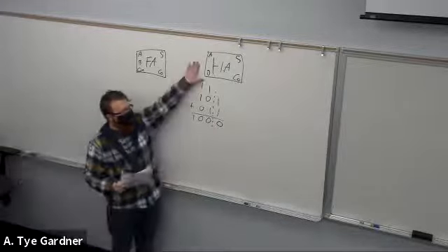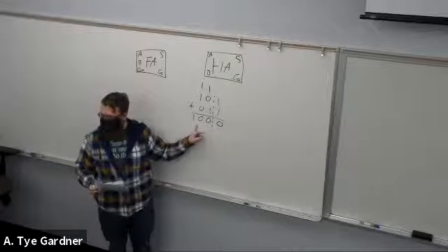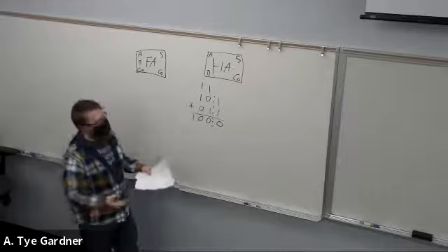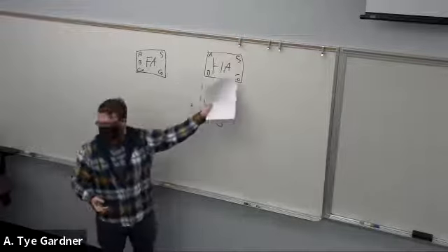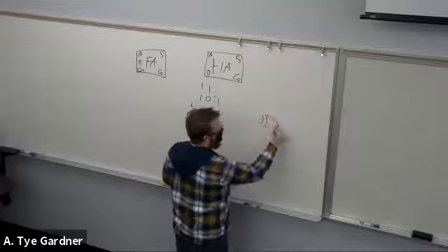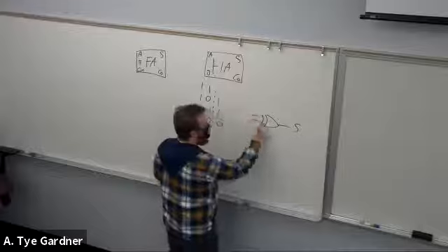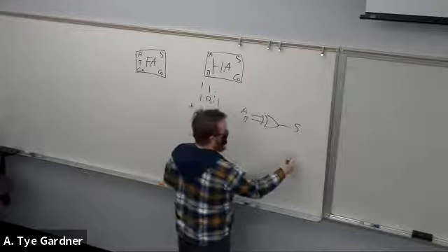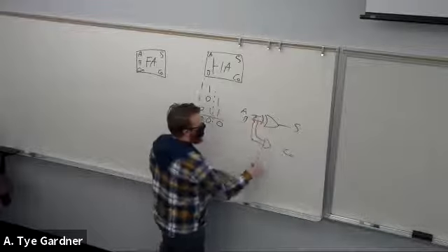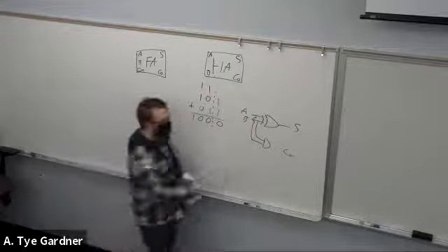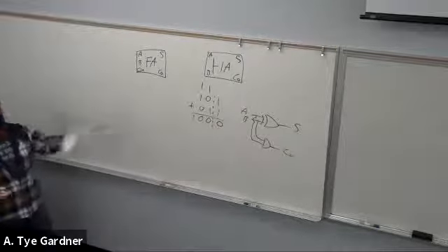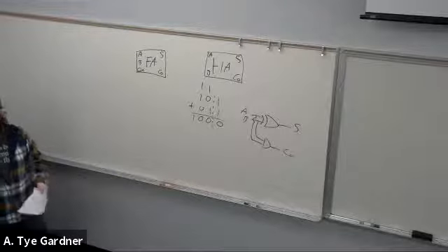The half adder functions for one column, but it doesn't work after that. The half adder, right, we could just draw the truth table. It has inputs A and B and 2 different outputs, sum and CO, and they end up looking something like this is sum. And the carry out is really just an AND gate between A and B, right? Nice, simple circuit. It's easy enough that you could probably just draw that circuit without even bothering with a K-map or any other sort of simplification.